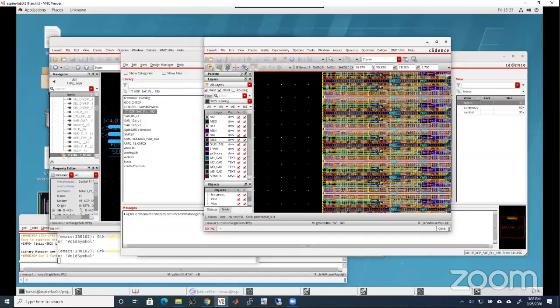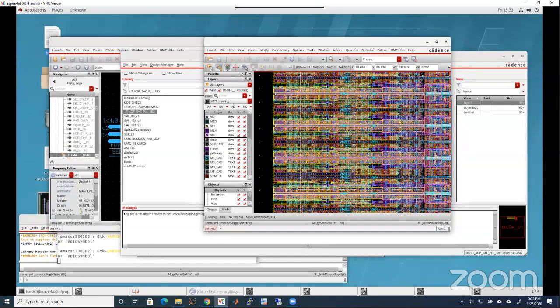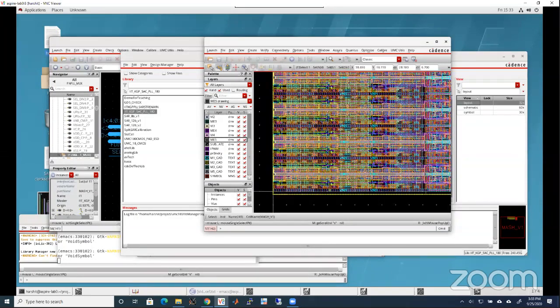Actually, I was trying to understand whether you have adjusted the height or along the x-axis like the previous one which you have shown. So these are directly the standard cells, right? These are standard cells. You never adjust the y height. Y direction height is constant. X direction it has to increase. There is no other option. You cannot keep both directions.